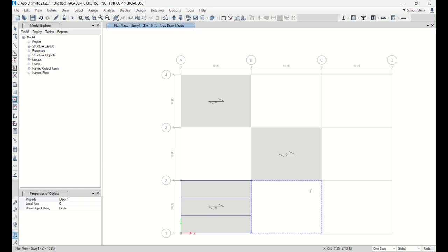Same thing with paper, if you have a form like this, right? It has stiffness in one direction. Because this is metal deck, you have a form like this, right? So the beam is here, let's say, this is beam and beam here. If you put this one, this metal deck has stiffness along its span, from here to here.